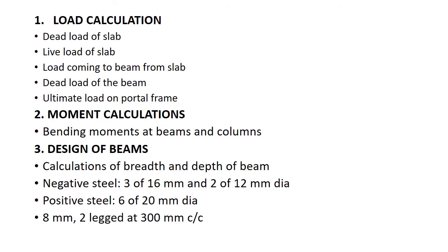So the designing part I am not going to do in detail. I will just explain it to you briefly. So what should be the design steps? The first is load calculation. In load calculation, first you have to calculate the dead load of the slab, that is, the self weight of the slab has to be considered.